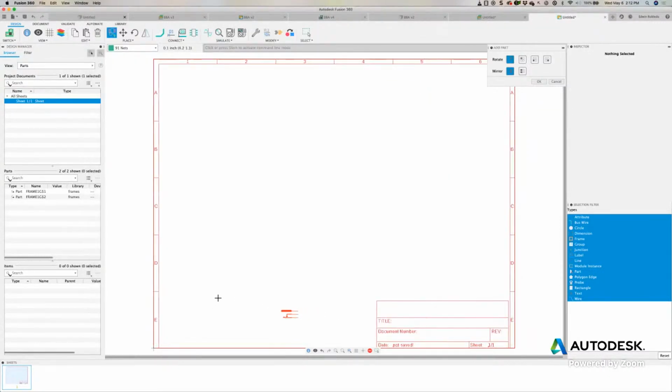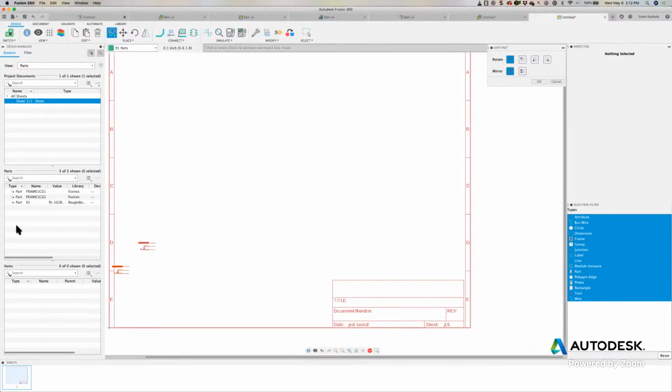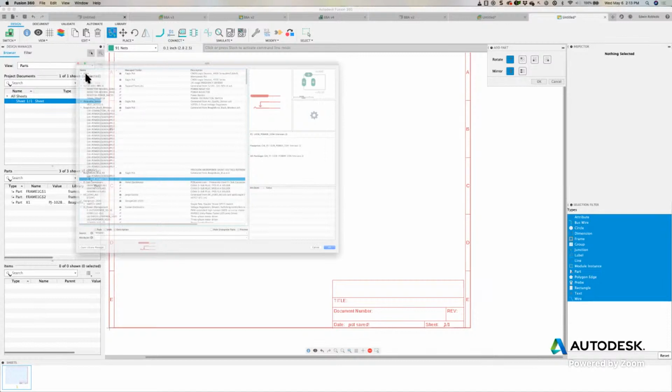Okay, so I'll go ahead and click on that one. And now I'm just going to add this on one corner of my schematic really quick. Now I'm just going to put some additional components that I'm going to be needing for this power jack. I need to bring in some representations of power that is actually going to power up the schematic. So I'm going to be plugging my power into this jack. And I'm not going to run a connection from this power jack to every component of my schematic. I'm just going to bring in a symbol that represents power and distribute that throughout my schematic. So let's go ahead and click on escape.